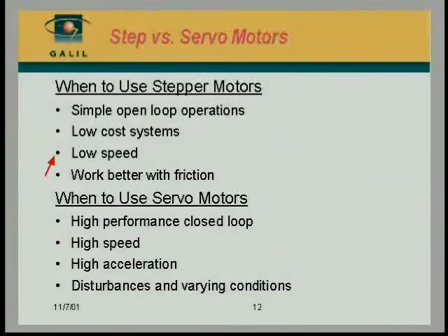Stepper motors, by their nature, produce a reasonable amount of torque, but at low speed. Once the speed increases, the torque drops. So if you need a high-speed operation, they're not suitable for that, but for low speed, they would be fine. Another feature of step motors is that they like friction. They hate inertia and like friction. The more friction you give a stepper motor, the better it behaves, the less it would overshoot. So if you happen to have a system with friction, that would improve the odds of a stepper motor being successful there.